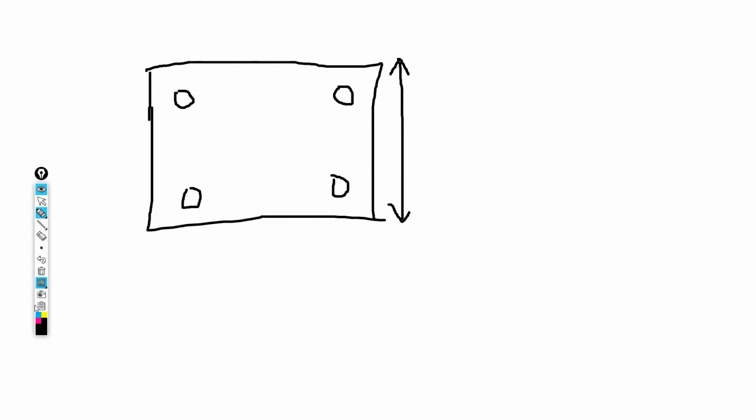Okay, I now need the space between face of reinforcement and face of reinforcement. So it's going to be 200 minus 2 times 30 minus 2 times 16. That leaves you with 108.